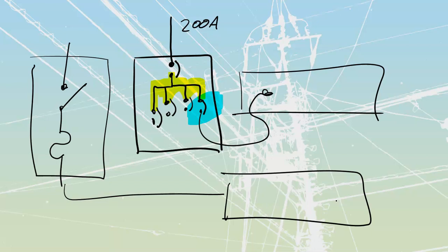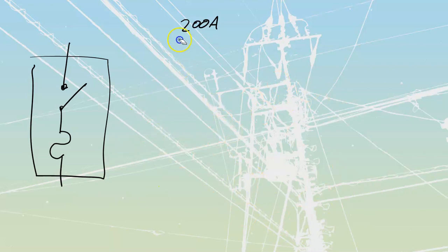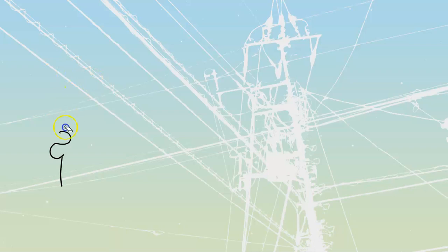Overcurrent protection needs to be done properly through all of our three-phase systems. And what we mean by properly is that we need to be able to interrupt the total amount of fault current that we are going to have. If we have a large installation, so we're going to give a value here of a 500 kVA transformer that we are using to feed out to a 120/208 volt secondary.